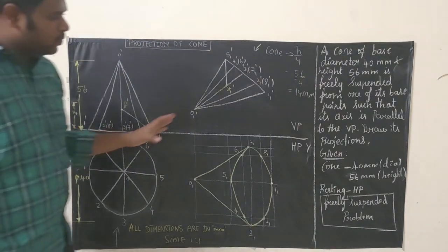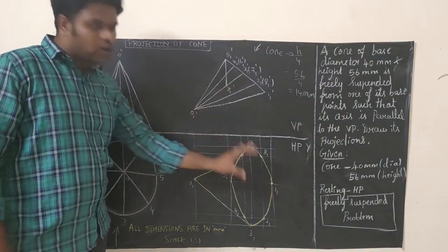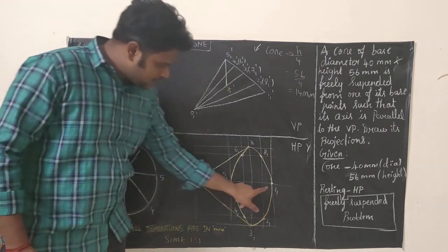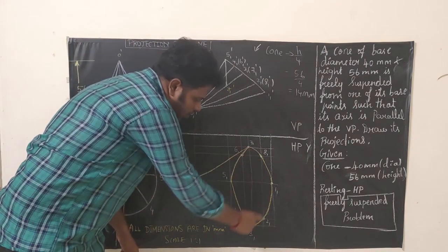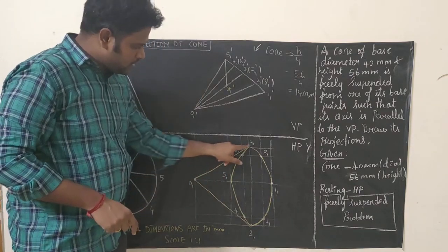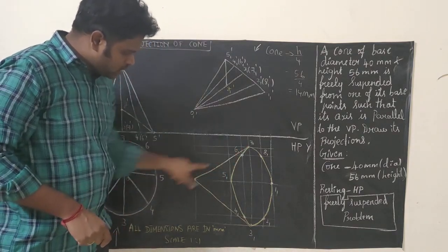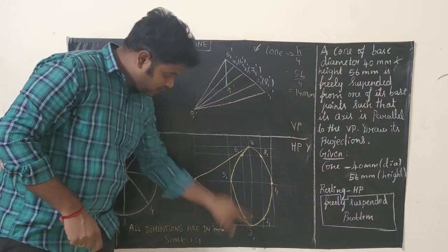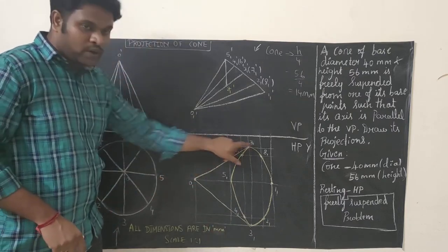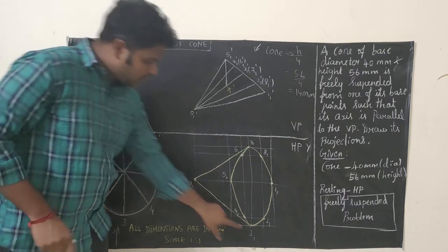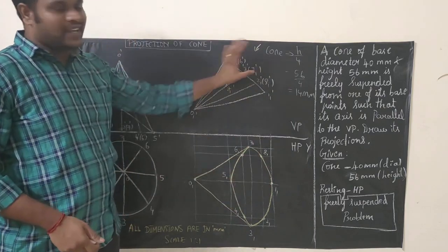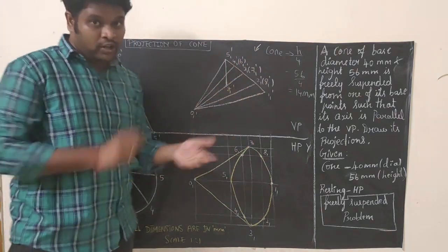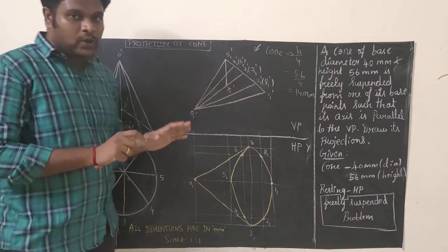So now what we did is we just connected all the points. First, you connect 1 2 3 4 5 6 7 8. Join all the points and then join the 7th point with O1 dash. 7 1 dash and O1 dash, 3 1 and O1. Join 7 1 with O1 and 3 1 with O1. This is our solution. Here we are seeing from here, right? So no hidden. We have not marked any hidden, so we just drew it as it is.